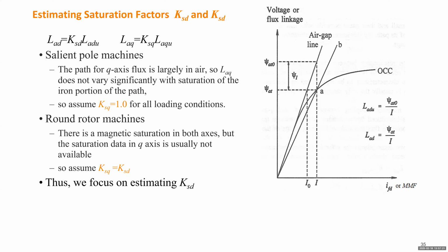Okay, so this curve will have almost the same slope before saturation. This means the curve is tangent to a straight line and stays very close to the straight line until a certain point, after which it separates from that line. So we can use this straight line as a perfect generator without any saturation. But when the load increases, the gap will gradually grow. Typically we can use an exponential function to model the gap between this curve and that straight line.